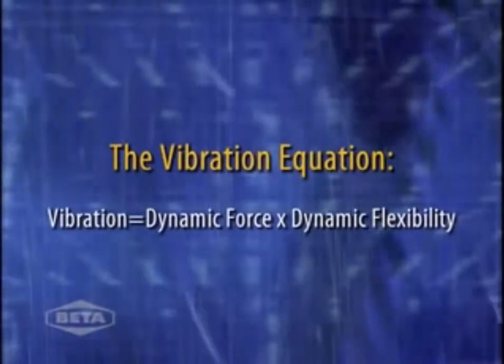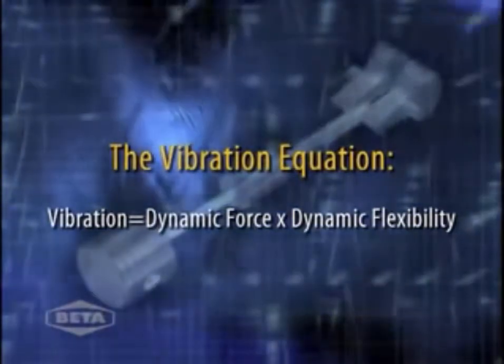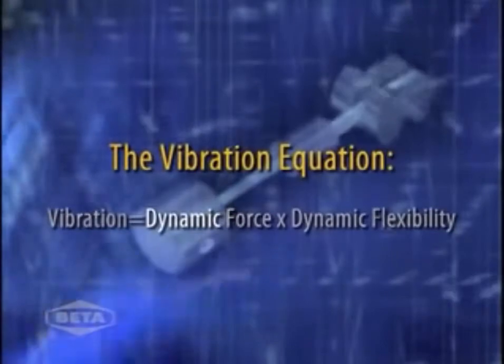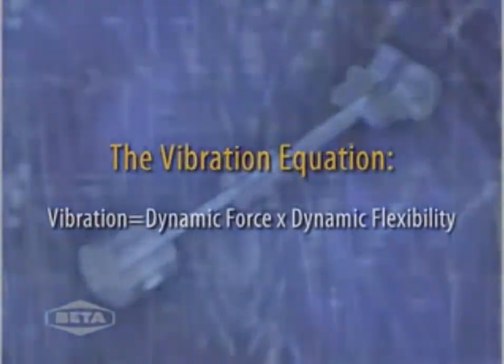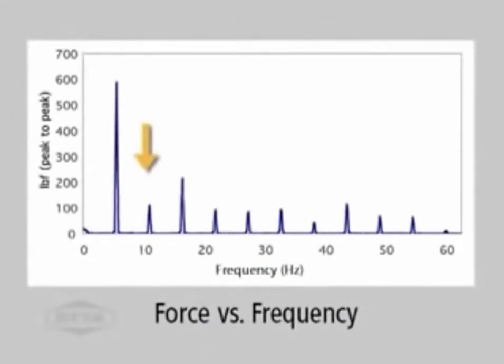Dynamic force is created by the combined motion of the piston, crankshaft, and other moving parts of the engine or compressor. The force is described as dynamic because it continuously changes in the course of each cycle. The dynamic force can be shown in a frequency diagram. The magnitude of force will vary with frequency.